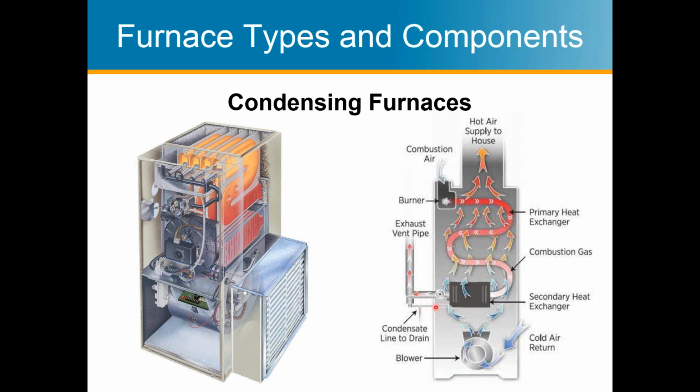So one of the other complexities of a condensing furnace is now you have to have a place to take the condensed water away. After it runs through a lime or something that's going to neutralize the acidity in it, the water can be released, and it's not harmful, but it's still going to go into the sewer system typically, or drift outside, I suppose.